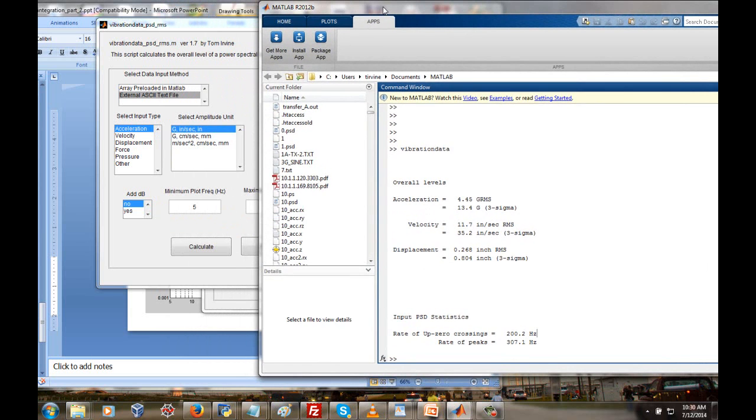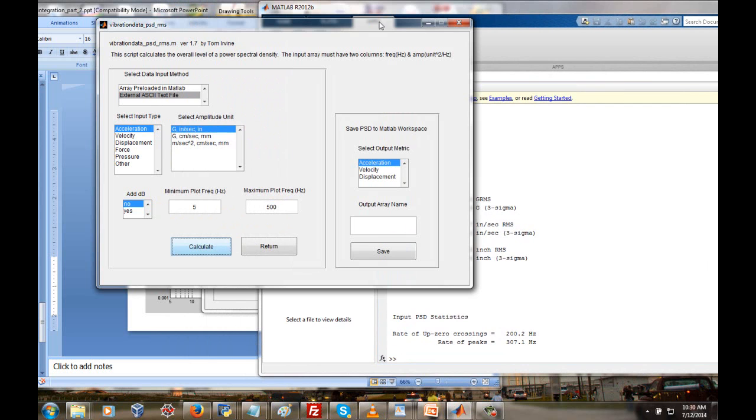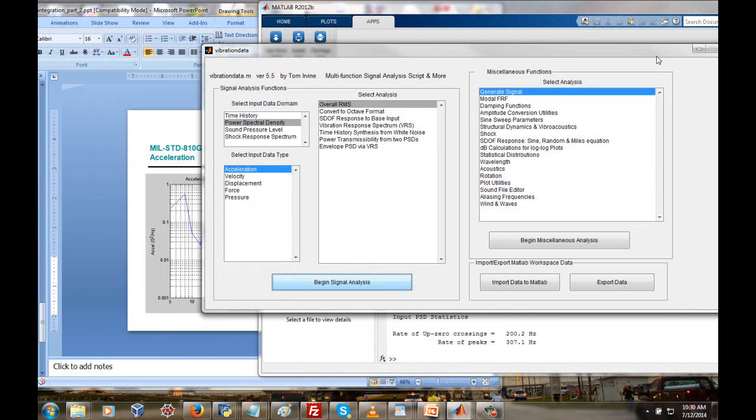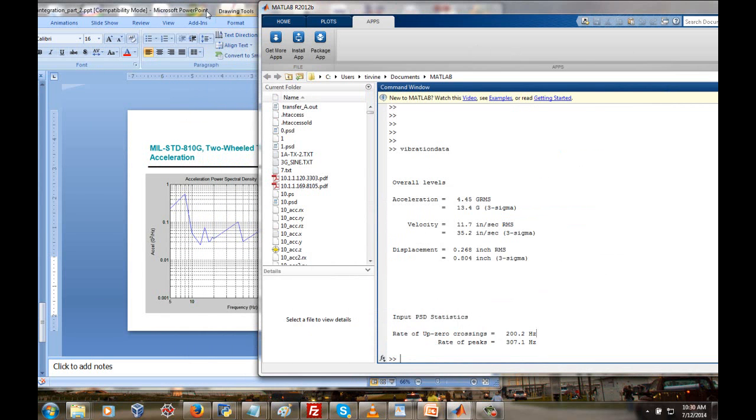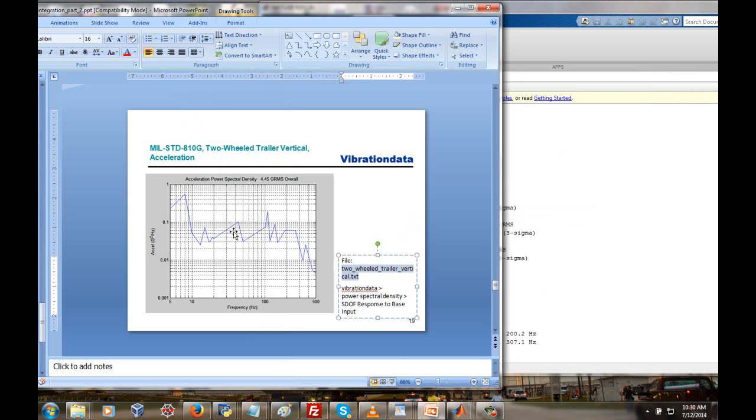Another thing we sometimes do is say, well, the natural frequency of our components is 50 hertz or higher, so what's going on below 10 hertz doesn't really affect as much, so maybe we'll just cut off at 10 hertz to limit displacement. Well, that might require writing some waivers and going through some review boards.